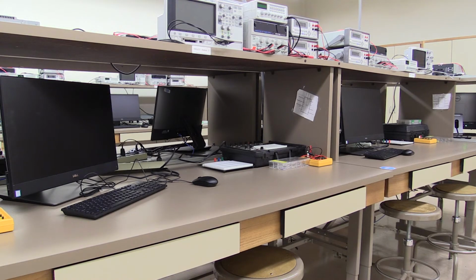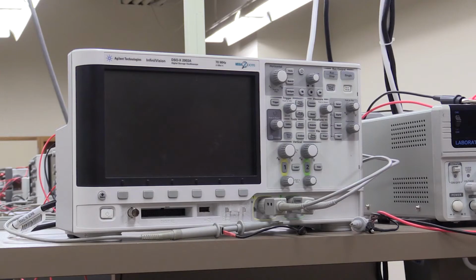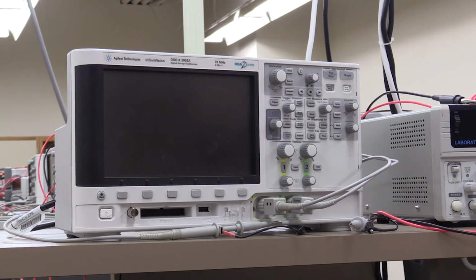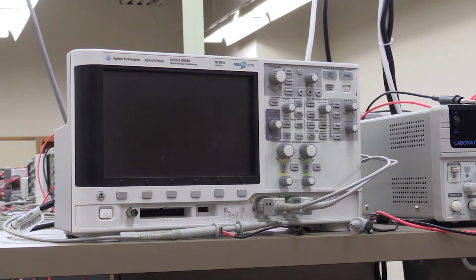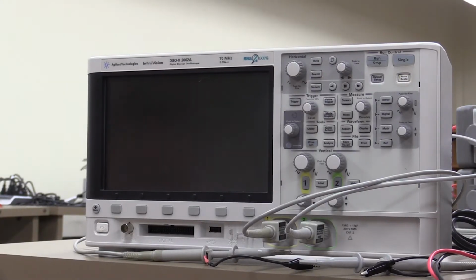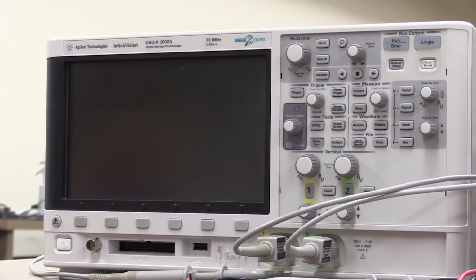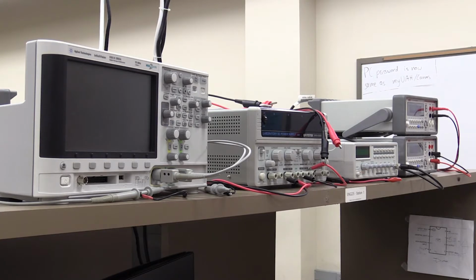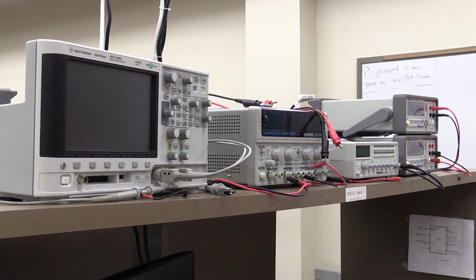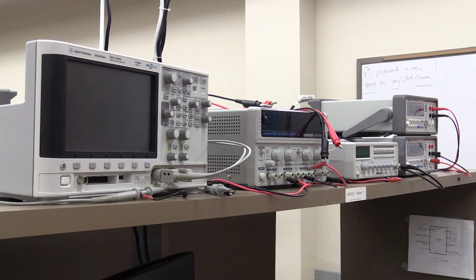Each workstation includes the following laboratory equipment: an Agilent DSO 2002 oscilloscope with 2 channels, automatic triggering, 70 MHz of analog bandwidth, and 2 gigasamples per second sampling capabilities that allow students to take time domain measurements. Additionally, these oscilloscopes provide math functions like fast Fourier transforms that may be used to view frequency domain behaviors. This oscilloscope is used to characterize operational amplifier circuits, rectifier circuits, transistor amplifiers, and filters via the time series waveforms produced.